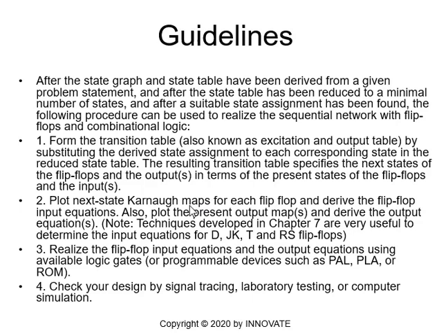Step number 2, plot next state Karnaugh maps for each flip-flop and derive the flip-flop input equations. Also plot the present output maps and derive the output equation or equations. Note, techniques developed in previous lectures are very useful in Chapter 7, are very useful to determine the input equations for D, JK, T, and RS flip-flops.